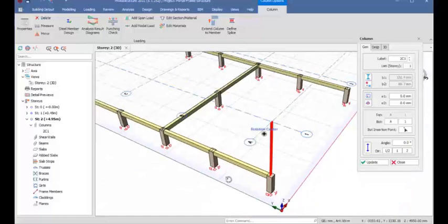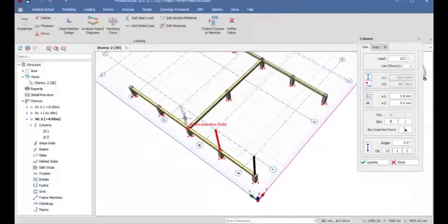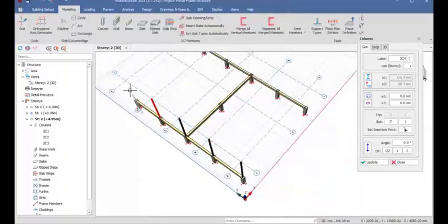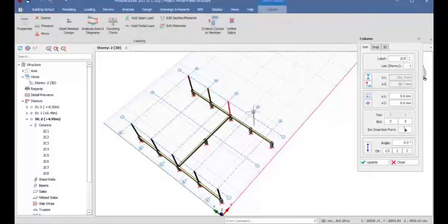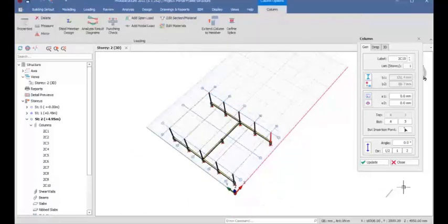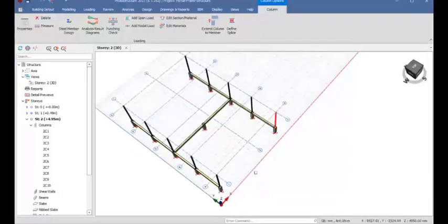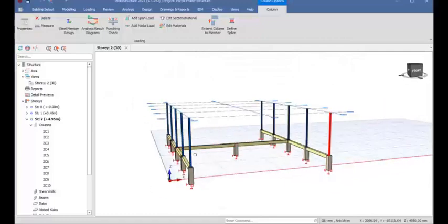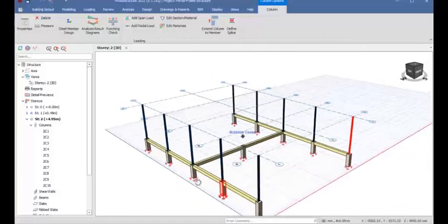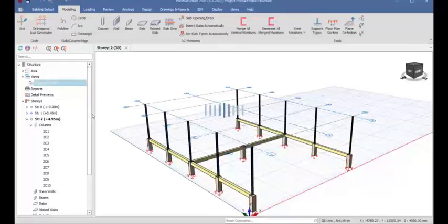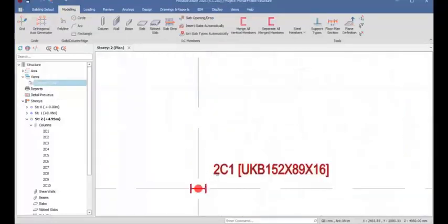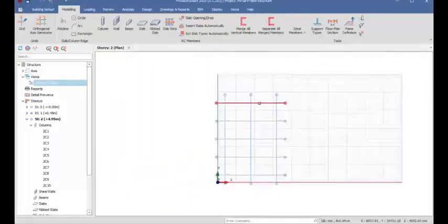So you continue to place that at these grid line provisions. The same thing in these other provisions. Then after which close this dialog. So we have this now. Can't we place it in the plan? You can also place it in the plan, but you must make sure you are at story 2, and then navigate to the plan view of story 2, so you can see the beams we placed here.